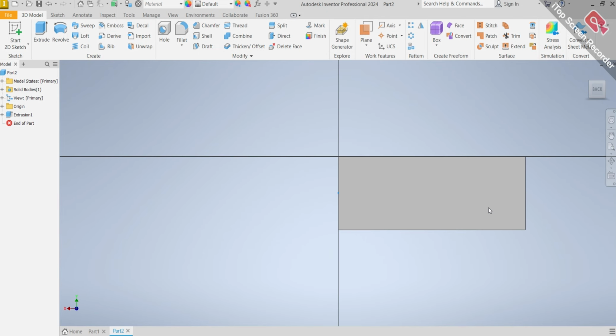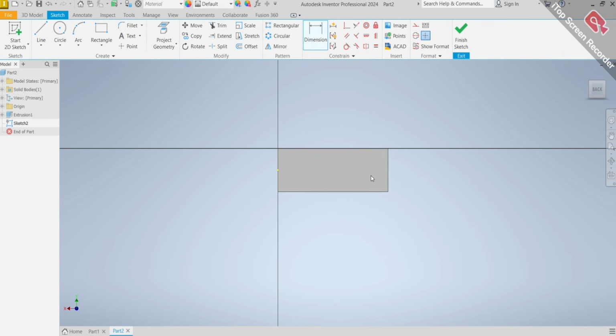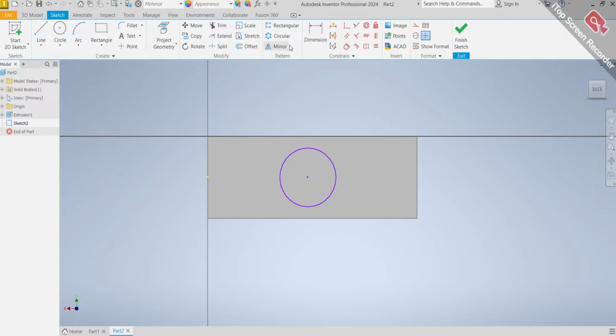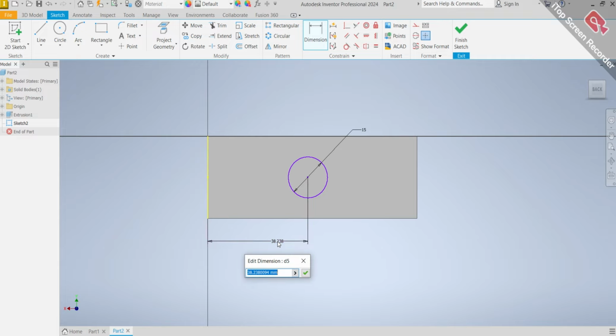Sketch. We have something like this. We come to this point here. Watch please. I'll try as much as possible to make sure it's in the middle, but if it's not in the middle, I'll see how I can constrain it. First, I'm going to dimension it. I'll click dimension. I'll click this. First dimension, I'll make it 15. Enter. Then what's the distance from here to here? I'll make it 40, because we know that the distance is 80. So 80 divided by 2 will be 40.